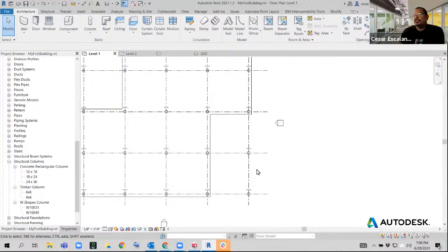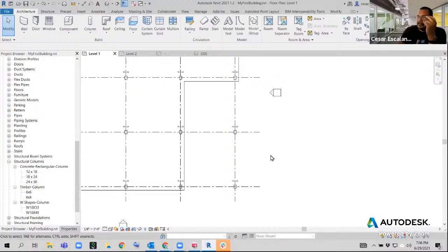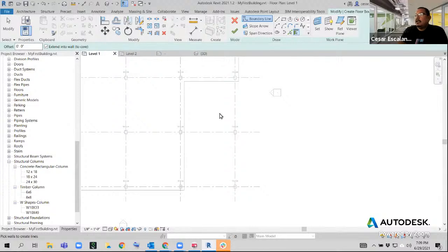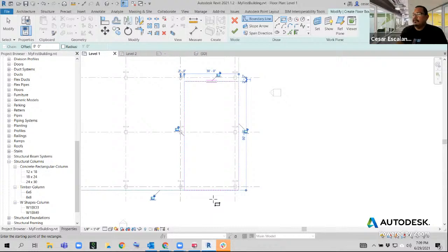And if you want to see the process, then I'm going to cancel and do it, and you can do it again on yourself, or we can do it together. So first, to do a slope floor, you enable the floor command, and then I'm going to create a rectangular floor. I use the rectangle tool, snap from this corner to this corner. If I hit my green checkbox, this is a flat floor. But what I want is a sloping floor.